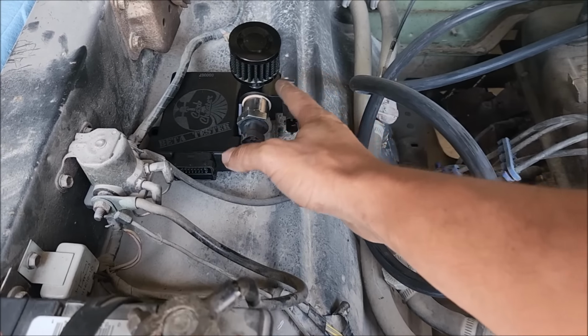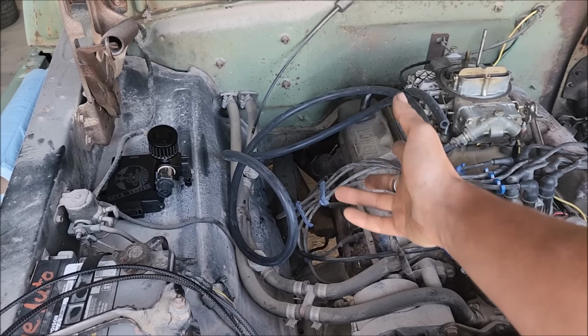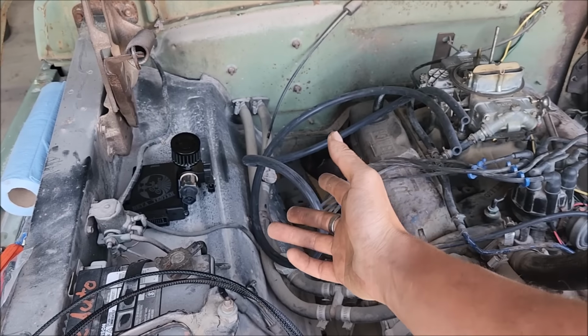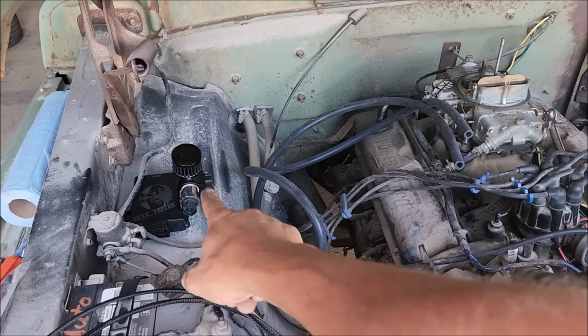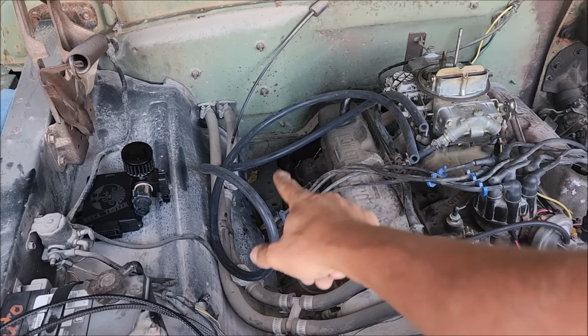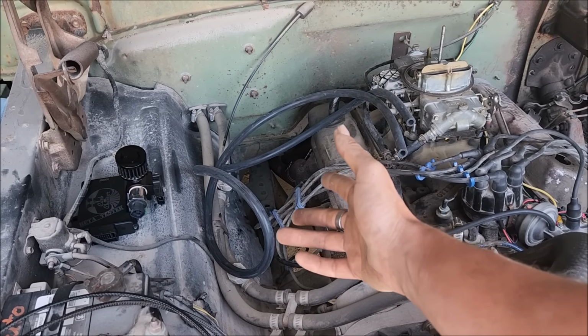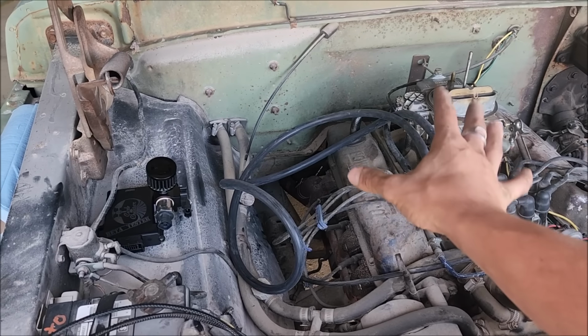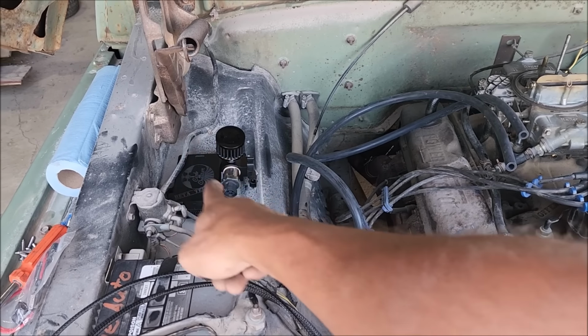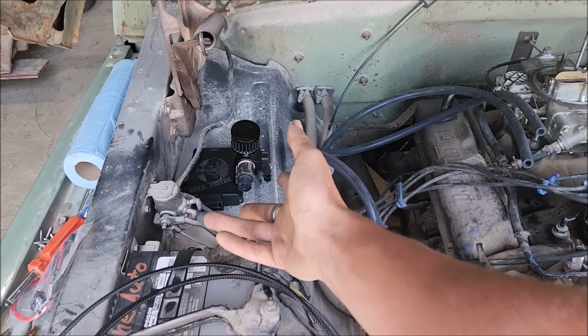Now on the part of the valve, you can actually mount these in separate locations. We did provide in the kit an extension kit, so you could install the valve closer to the engine on the intake manifold if you really wanted to. Now, very loosely here, the bigger the engine, the nicer it is to have the valve closer. Obviously, the more tube you have, the more restriction you have, but really it doesn't take a whole lot to make a huge alteration in your air-fuel ratio. So for now, we're just going to leave our box here and it'll be pretty easy.